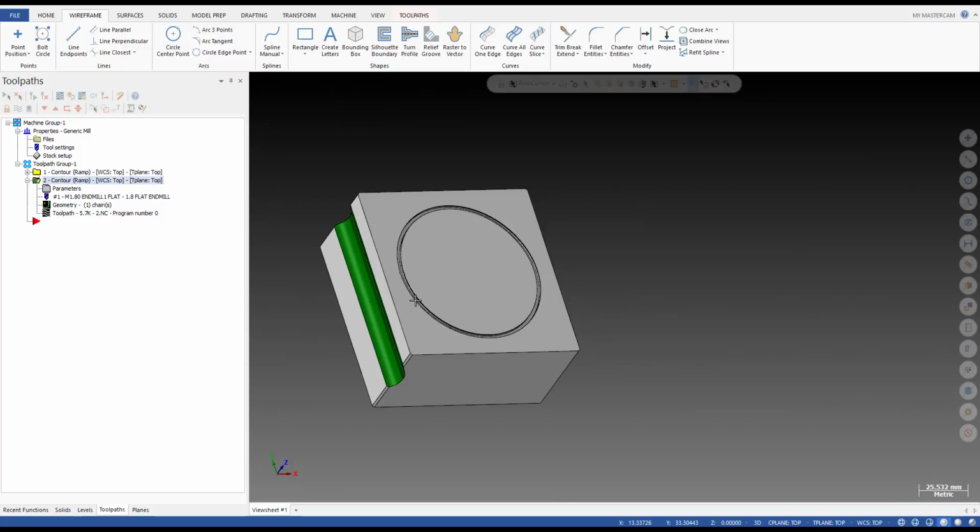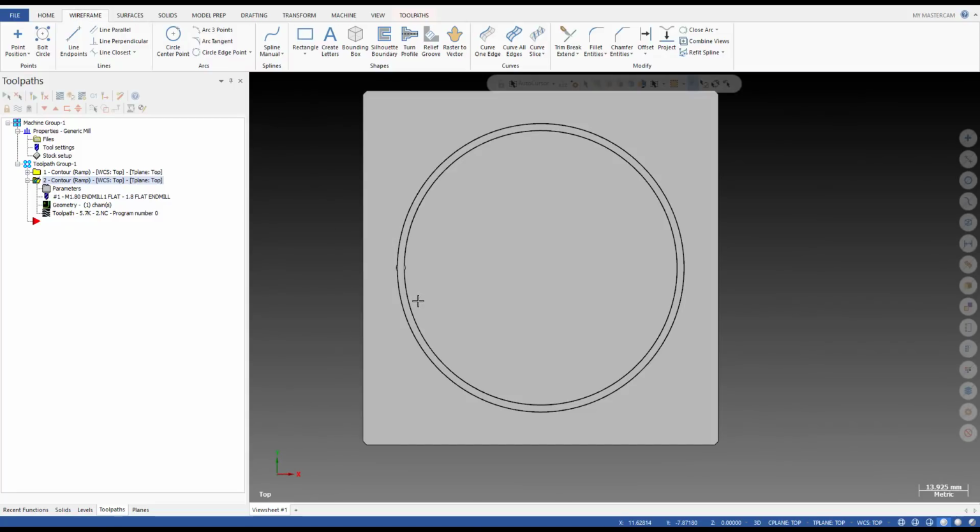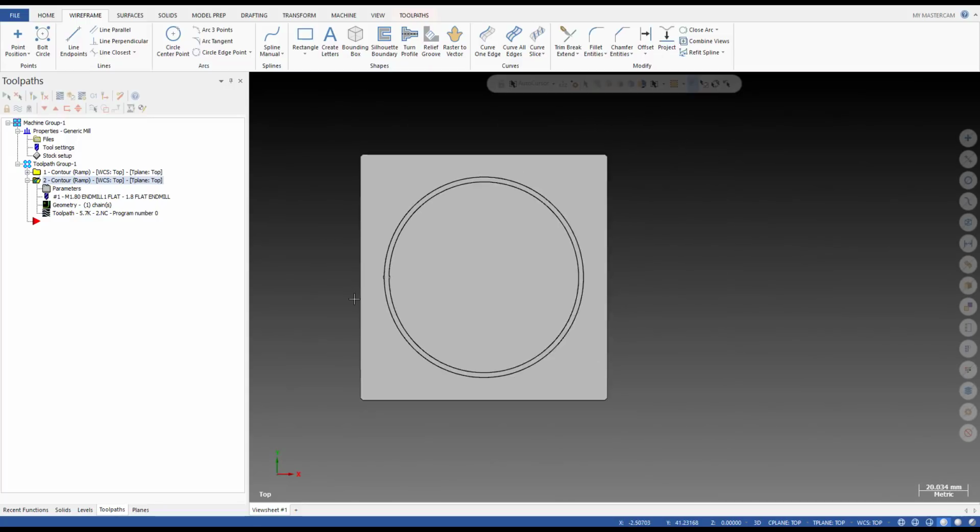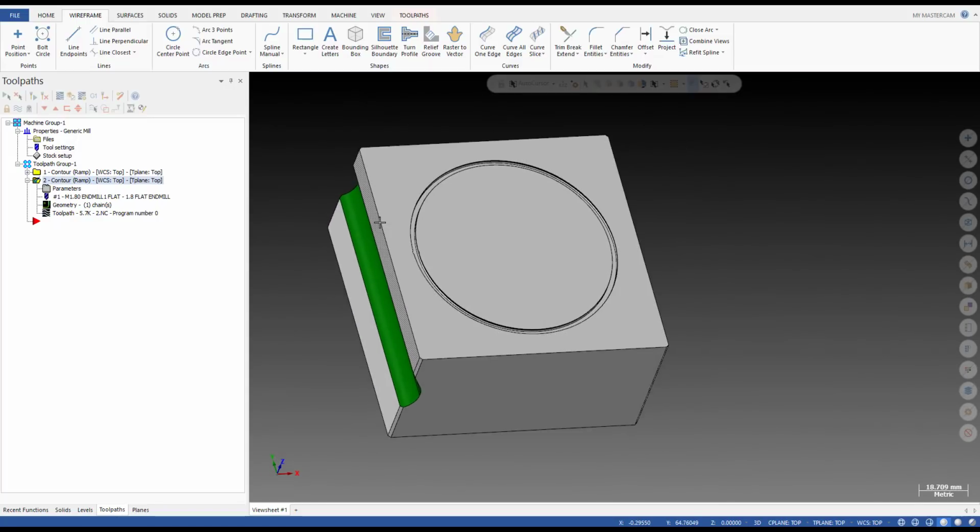And in simulation, if you do not define the correct geometry of the tool, you will not get a correct simulation. So you are unable to see how the part looks after it's cut with the custom tool. Okay, so defining a custom tool is very important. And today I'm gonna show you how we can do that, how we can define a custom tool, and whether there is any rule for creating a custom tool. I will cover that in this video.